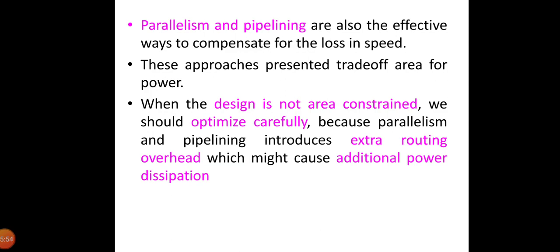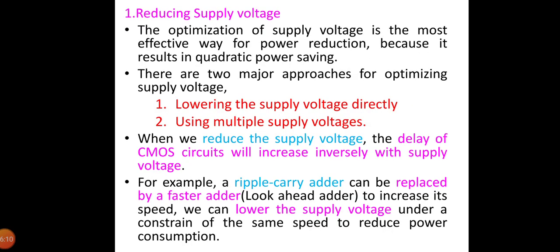And the supply voltage cannot be reduced any further because no extra delay can be tolerated. So we use this topology as the reference data path for our study and present power improvement numbers with respect to this reference. The average power consumed by the reference data path will be P_reference = C_reference × V_reference² × f_reference, where C_reference is the total effective capacitance being switched per clock cycle.